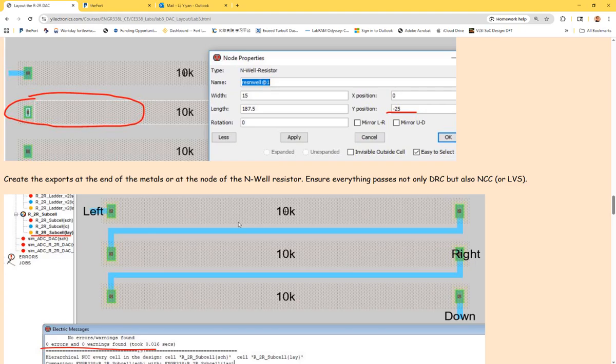But now it's still inside the chip. We are not just directly using the resistor for the final design. It's just a chip. In the final design, if you are using this DAC, you are going to have metal 3 eventually, but now it's still a subcell, even for the DAC, it's still a subcell in the library. Okay? So we don't really need metal 2 and metal 3, just metal 1, which is fine. You just leave the ports available in the future. When we use the DAC for a bigger design, we can connect all the vias to metal 2 and metal 3 in the future.